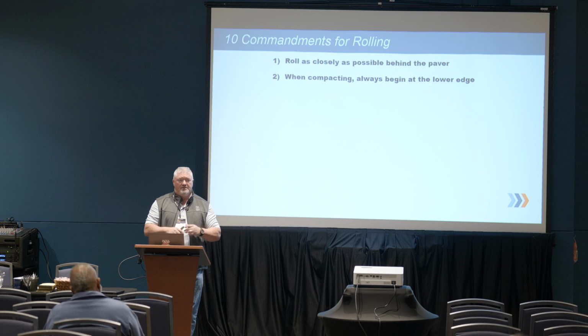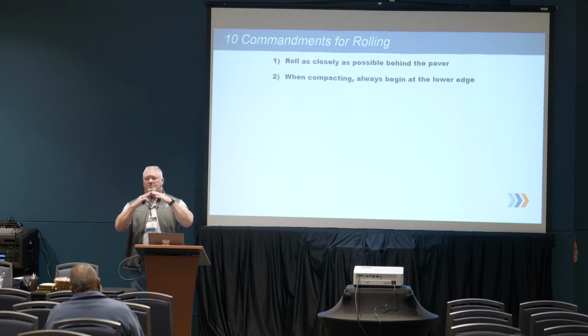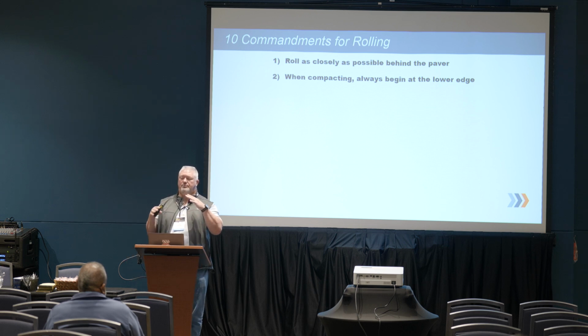I always like to start compacting on the lower edge. All roads have some kind of a slope. A lot of people like pinching the joint first. I don't like doing that. I'm not saying it's right or wrong. I just don't like doing it because if I do the outside lane first, I am compacting and resisting anything to move out away from the joint. And then I'm going to work my way up to the joint.